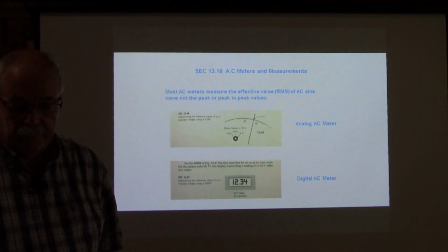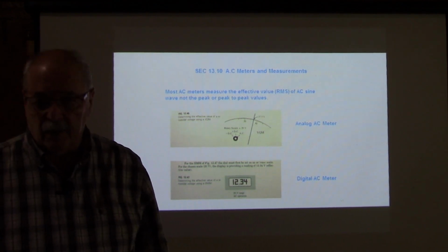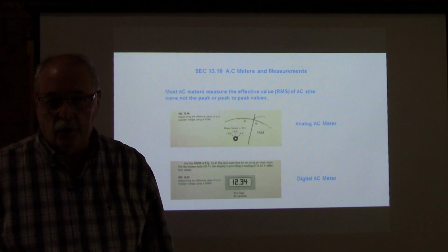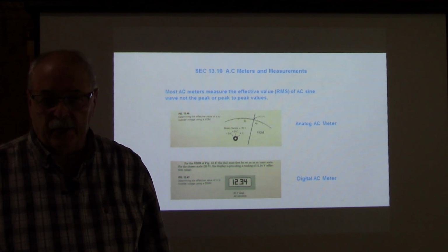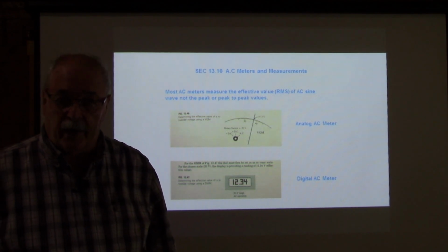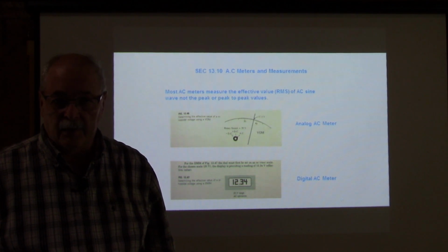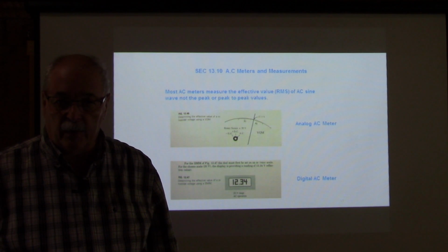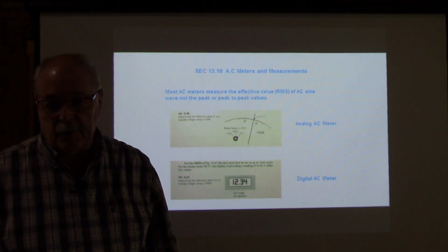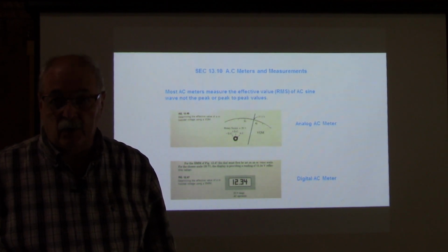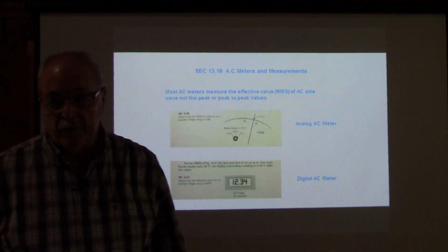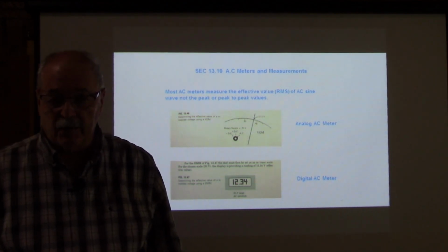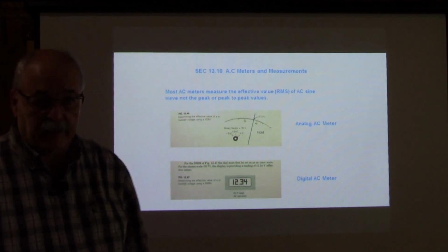I might have mentioned this, I think I did in the first part of the lecture. Your function generators or signal generators always default to triangle. You have to remember always to press the sine button, the little symbol for the sine, to make it work in sine. All right. Especially if you're not using an oscilloscope and you actually don't see the waveform, and you're measuring with a meter, then you could have some pretty tragic results because the meter doesn't like triangle waves very much. It likes to see a sine wave.